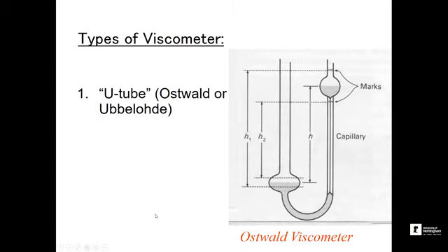But then you pump. Used to blow through a tube at one stage, which would never be allowed now in health and safety. But now it's done by automatic pumping, which pumps the liquid through the capillary into this second bulb here and above this mark, and then either manually you switch off the pumping device, or expensive instruments have photo detectors so they can sense when you get past this mark.